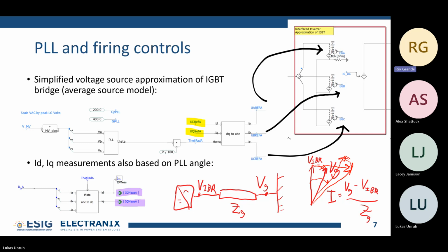So you can run into situations where, if you have some overshoot on your current control loop, you can maybe move the system angle substantially to a place where you now want to move your inverter angle in the other direction, and you basically get these phasors eventually just oscillating out of phase with each other, which is kind of the underlying mechanism for weak grid instability as well.